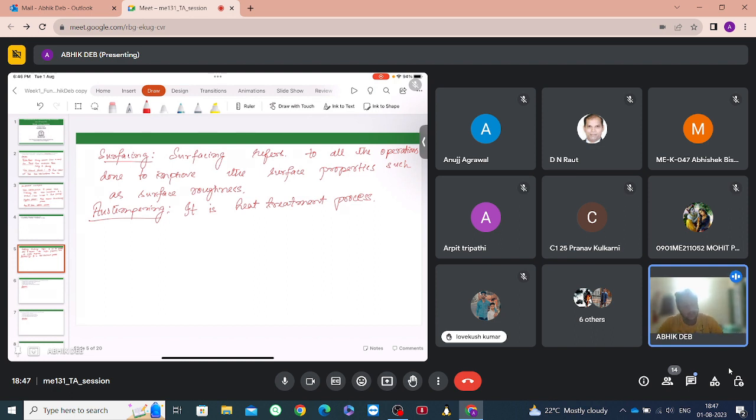So from the steels that we use, basically the medium carbon steels, they have either a high hardness or a high ductility. To improve these properties, we heat these components and then cool them such that a microstructure called bainite is formed.